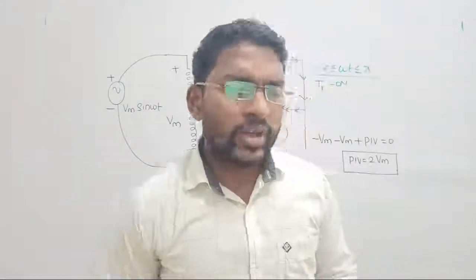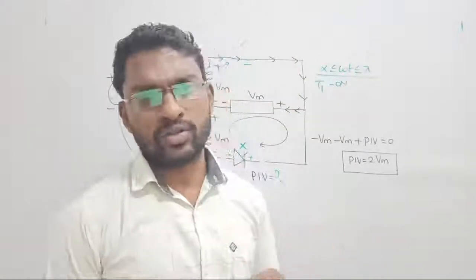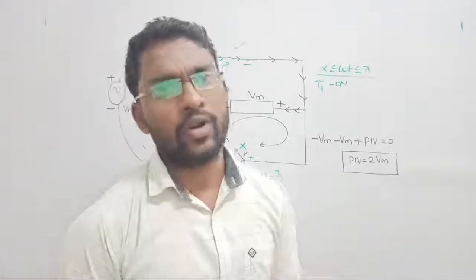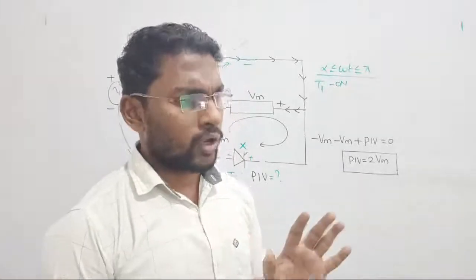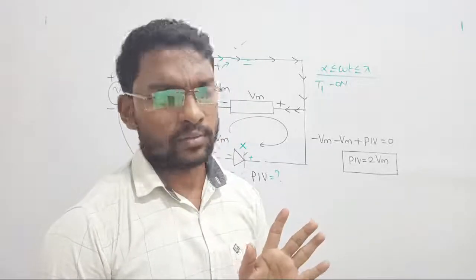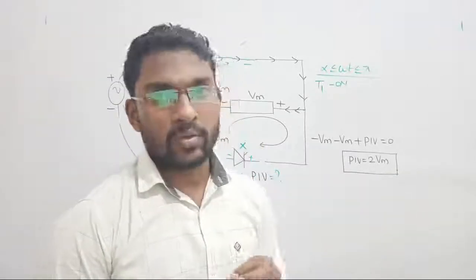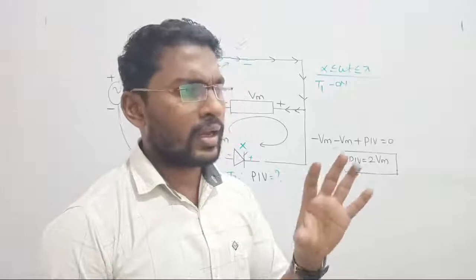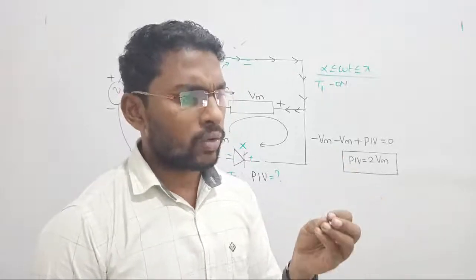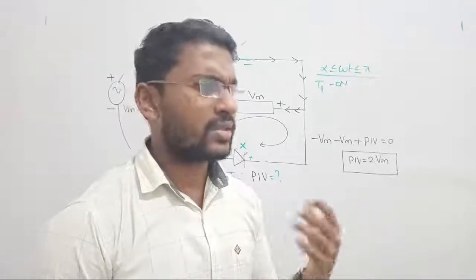But as I said, we can also do all these things with the help of uncontrolled diodes. That's why uncontrolled switches are simply called diodes. Designing the diodes is not a big deal for you all. I am repeating once again: the only difference here is that for diodes we don't need to give a firing angle. When the supply voltage comes, they turn on automatically. So in whichever cases we saw earlier where there was a firing angle, that is alpha, if you put alpha as 0, then that circuit will resemble the property of a diode. Clear? Yes.